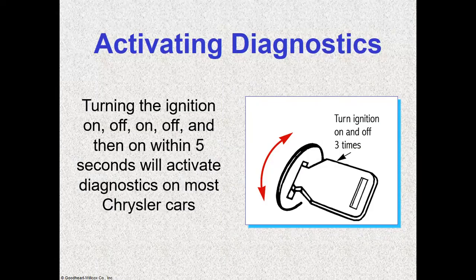And this other one says turn the ignition key on, off, and then on within 5 seconds. That will activate diagnostics on most Chrysler cars.